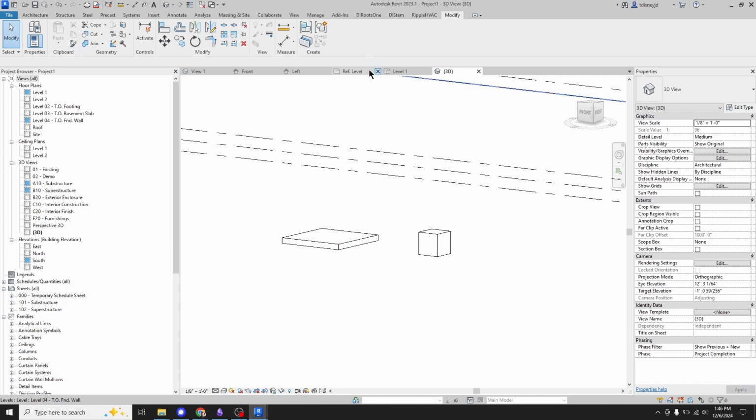So one versus the other, you should understand what you're doing when Revit asks you if you want to override the parameter values or not, because you can destroy information. Let's say that you load a family into your project, and then you add a bunch of schedule data to the shared parameters in that family, and then you open up that family from an external source. So you're in the family editor, but you didn't open it from the project. You opened it from wherever it lives on your desktop or your computer or your server. And that version of the family won't have that new schedule data.